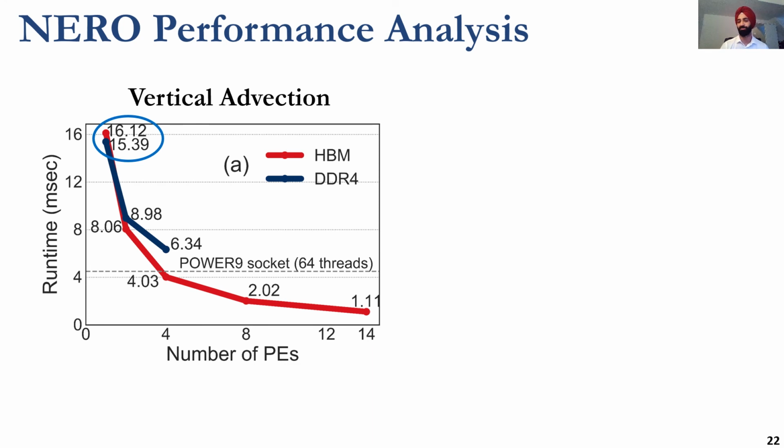This leads to a lower transfer rate for an HBM port. One way to match the DDR4 bus width would be to have a single processing element fetch data from multiple HBM ports in parallel. However, using more ports leads to higher power consumption. And our experiments show that this power consumption is around 1 watt per HBM port, which is allowed.